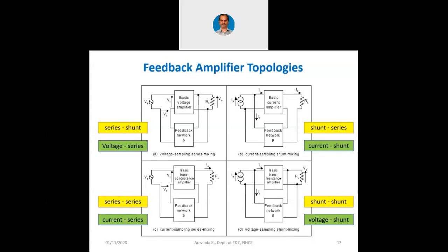waveforms. That means if one waveform is in the positive cycle, if the other waveform is in the negative cycle, the resultant waveform will be the subtracted version. If they are in the same phase, then the resultant waveform will be in the added version. But when 2 voltage sources are in parallel, we have difficulties, because whichever is having the largest potential is going to be dominant. We cannot say that a linear addition or a linear subtraction is going to happen there.